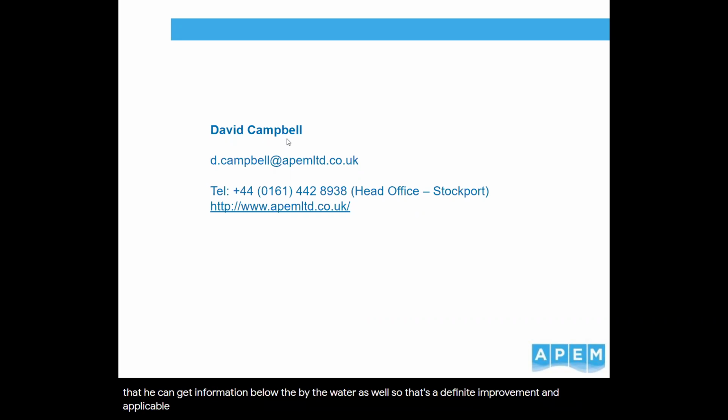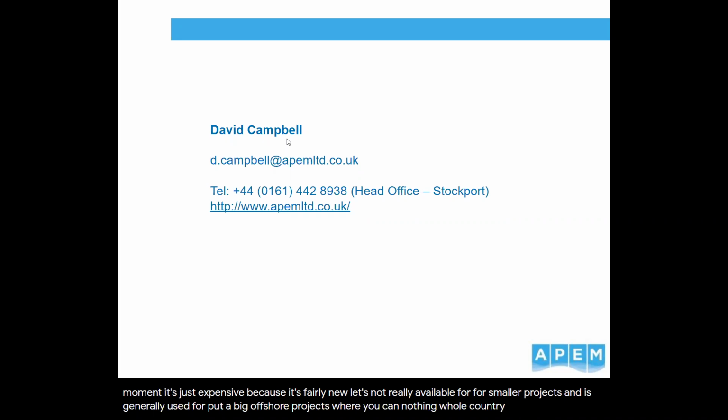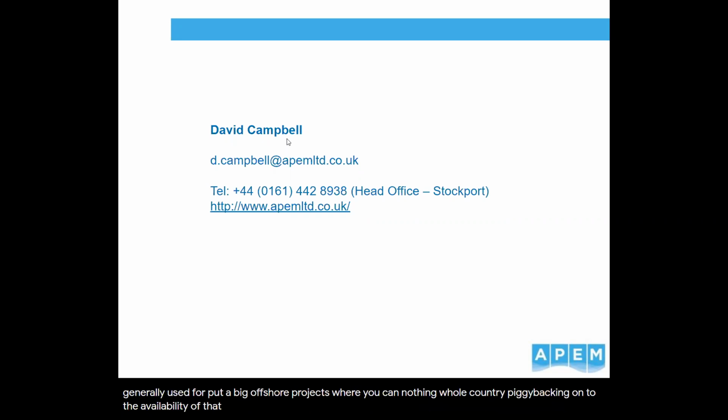So that's a definite improvement, and it's going to be really applicable. The barrier at the moment is just the expense of the kit, because it's fairly new. It's not really available for smaller projects, and it's generally used for big offshore projects where you're mapping whole country coastlines, for example. However, there are projects piggybacking onto the availability of that, where they're doing a big survey somewhere else and then piggybacking onto a river survey. So I definitely wouldn't rule it out. And if anyone is interested in bathymetric LiDAR surveys, please do get in touch.